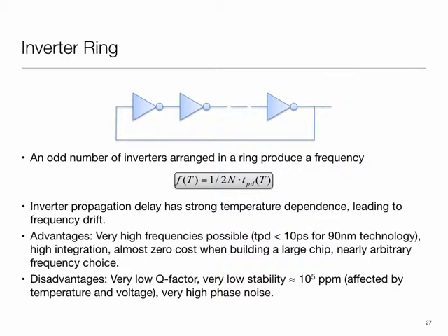So usually, because they can start very rapidly, when your system starts up and you just want to start executing instructions, that's a reasonable thing to do. And usually the microcontrollers then have some sort of signal where you can say that now my external clock is stable, and then you can switch over to that. So the model typically tends to be, you start up using the ring oscillator, and after a short while you switch to the more stable clock. This way you benefit from rapid start, so you are not sitting idle, but then once your stable clock is available, you switch over to that.